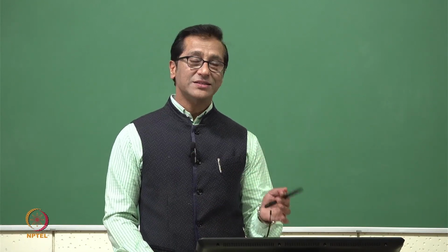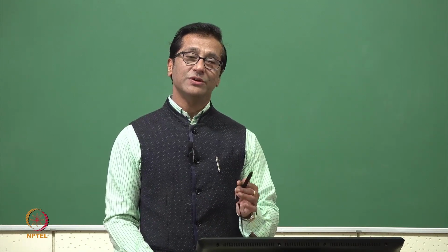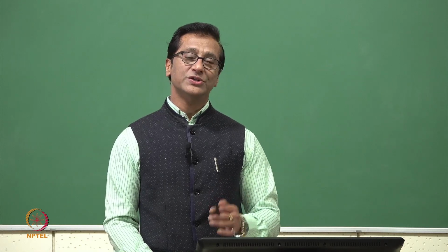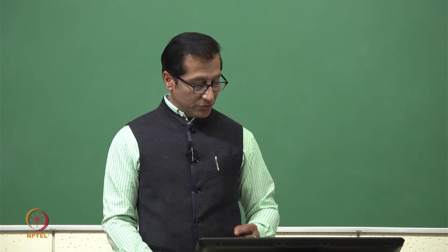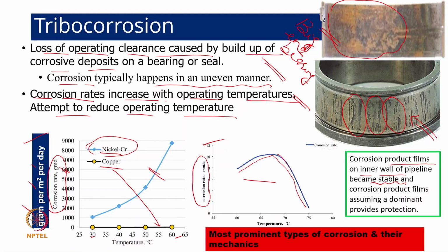But in the presence of tribology, in the presence of wear rate, abrasion, and erosion, whatever stable film thickness has been made will get ruptured and removed. So instead of going down this side, it can again increase in this manner. So this is with tribology, say without wear, and this will be with wear.